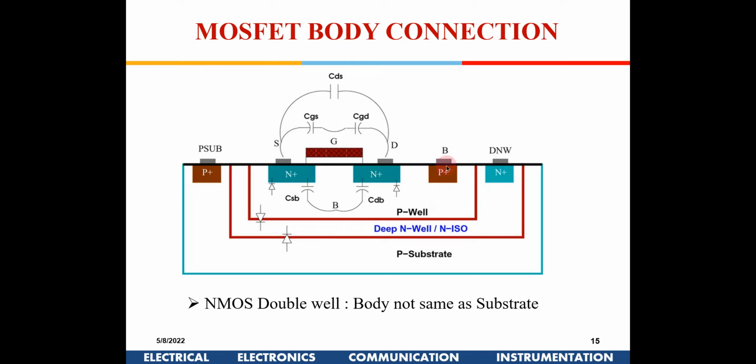Okay, so here you can use, in fact, in certain circuits such kinds of devices are also used, where you can modulate the threshold voltage by giving a separate voltage to the body out here, right? You have low VTs required in certain applications like RF rectifiers and all. So these kinds of things can also be done.